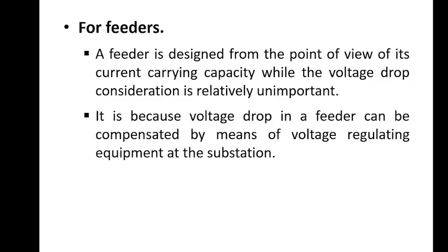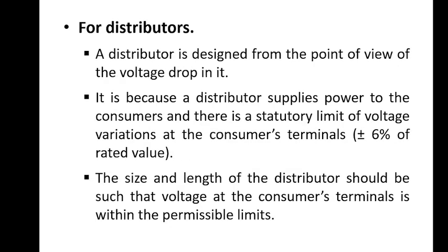Therefore, the main priority in feeder design is to ensure adequate conductor size and capacity to handle load demand, while voltage control can be managed separately at the appropriate substations.